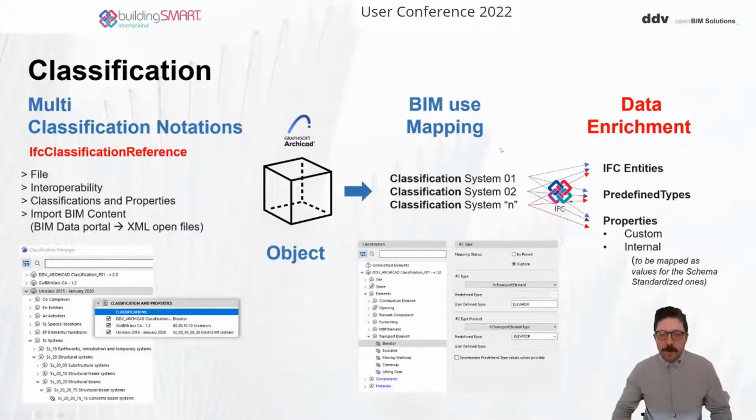And remember that in our Open BIM workflow, we first of all define our goals. So we define our BIM uses, and we are creating our models according to those uses, right? So each of those scenarios could be aligned to those uses, which means that we can create different IFC based models using different classification systems. So we will apply a different classification mapping rule to each of our IFC exports according to those different BIM uses.